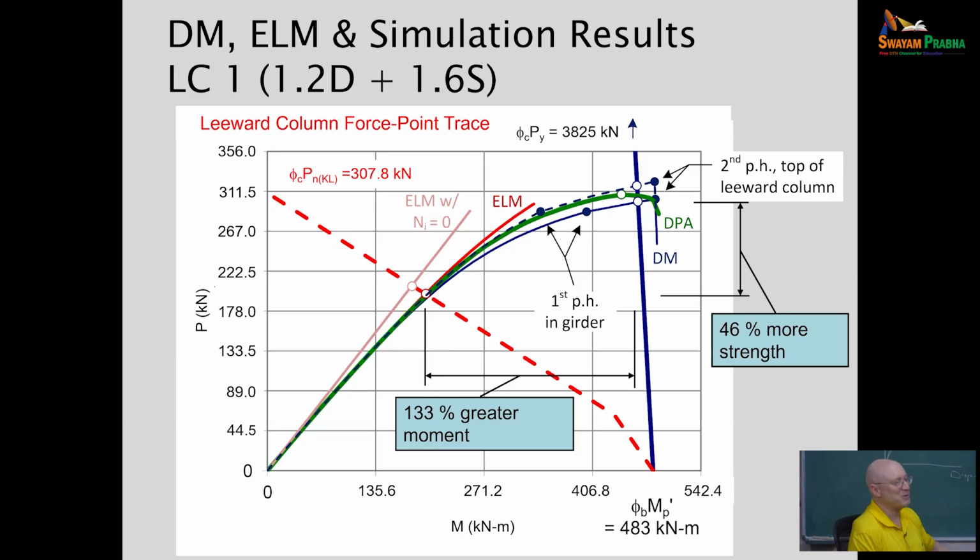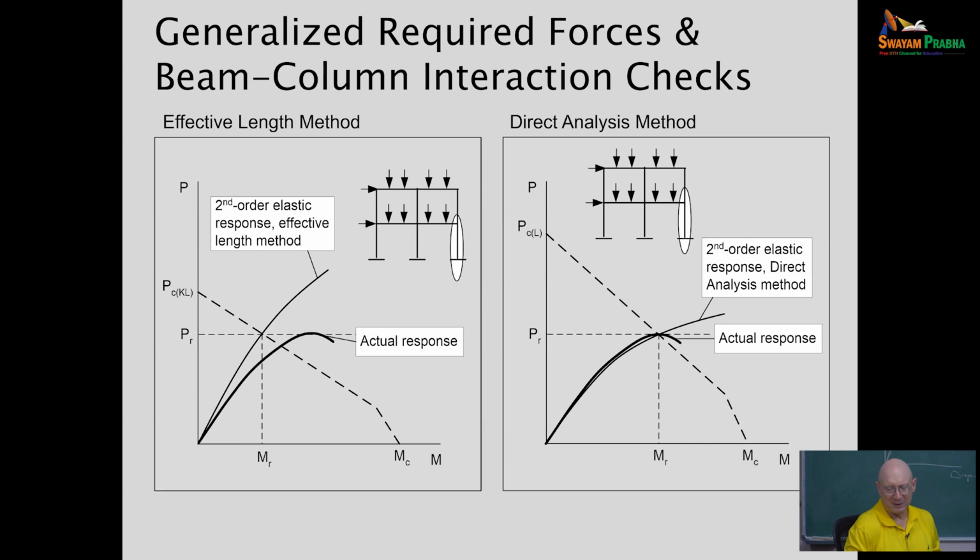Okay. Yeah. Thank you. Yes, everything up to this point, we were just talking about elastic design, and then I took it a few steps further here to say, okay, we tied it in with a plastic hinge formation to evaluate the capacity of the frame. So this is a graphic to try to maybe get closure and make sense out of, is the effective length method okay? We've been designing for that since the beginning of time, and things aren't falling down. It's generally okay, but what's going on?